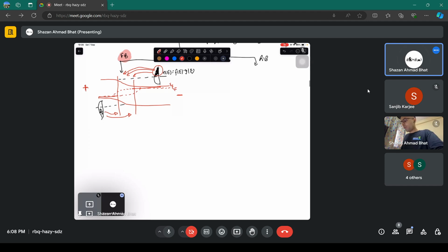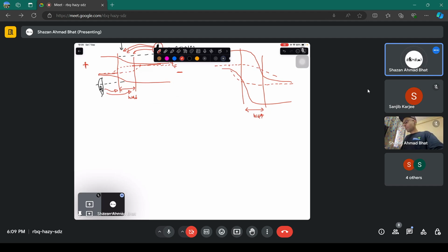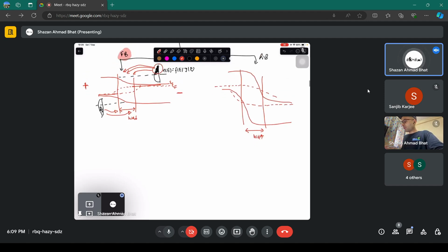And what you then showed is that if you consider the reverse bias case, you have something like a huge barrier present between, where this is the Fermi level of the N side, this is the Fermi level of the P side, and in between the Fermi level looks something like this. And this is the depletion region, and the depletion region width increases appreciably under the reverse bias. Here, the depletion region width decreases under the forward bias. So this is what you have covered till now.